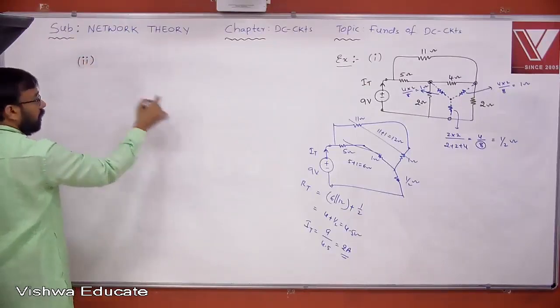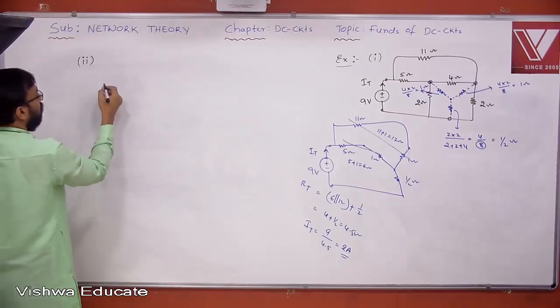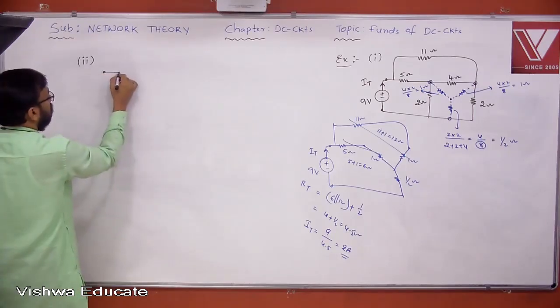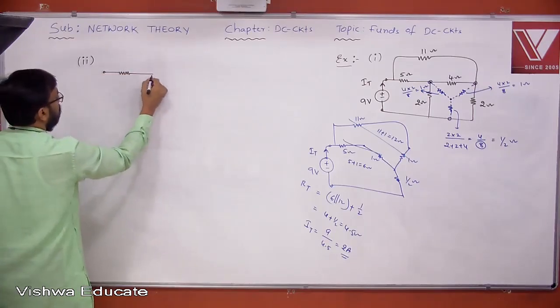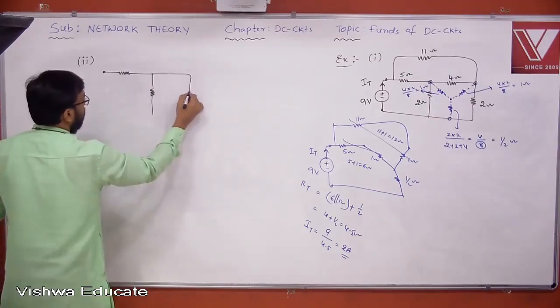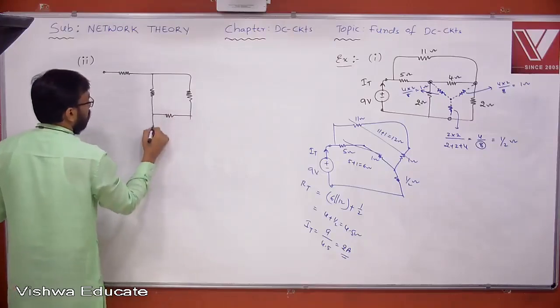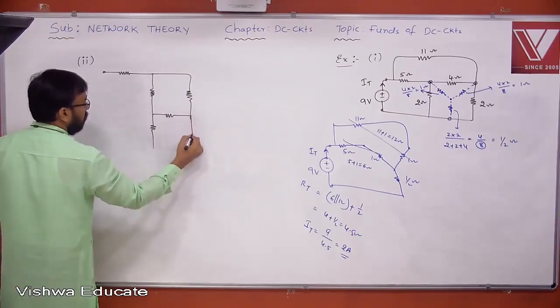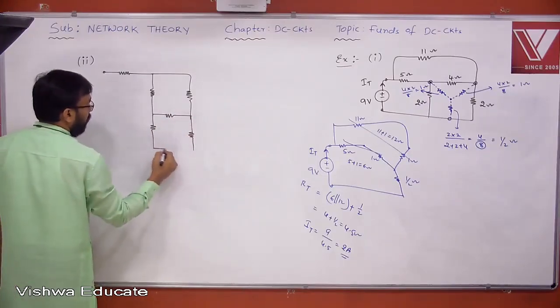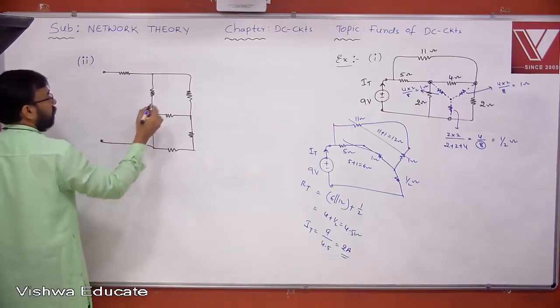Note down the solution, all of you. Meanwhile, I just give you another problem. So star delta transformation you apply when all elements are neither series nor parallel. When all elements are connected neither series nor parallel, you can go for star delta transformation.